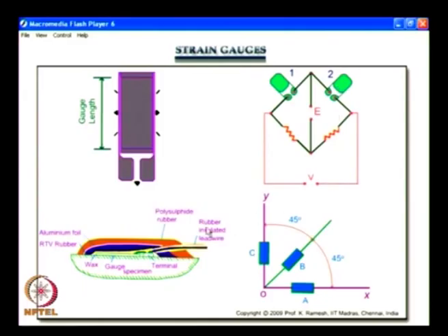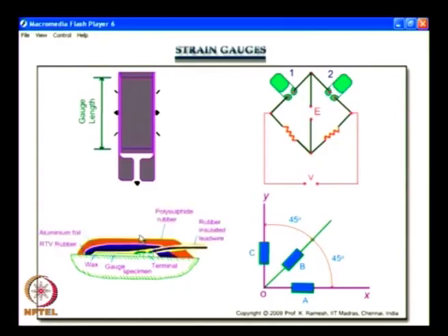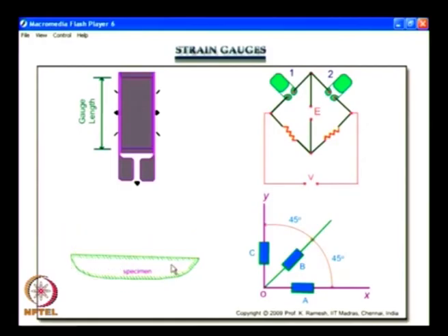Then you have how strain gauges need to be protected in aggressive environments, that is also very important. You have several layers of coating applied, particularly when you want to do it underwater, on piping, and anything to do with that kind of aggressive environment, you need a well protected strain gauge installation.